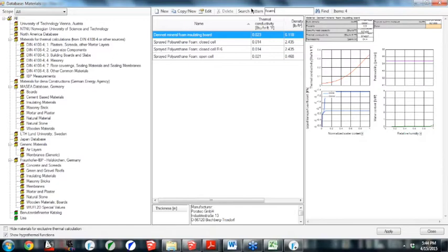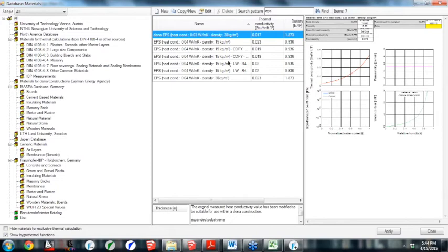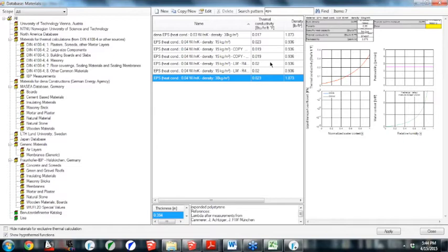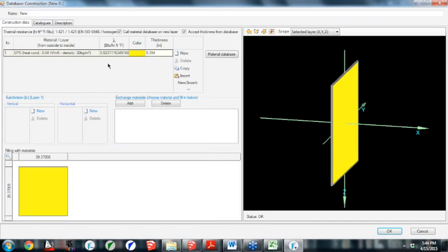It's pretty different in terms of the actual composition of the material, but what we're looking for, again, is just the R value. So yeah, the density of foam glass is going to be significantly higher than this, but we're just going to pick this value for the EPS and use the R value from it. What we could do, if we wanted to run a dynamic model, is actually find the information for foam glass and create a new material within our material database. I'm not going to do that today because we will run out of time, but that is something you can do. Okay, so we have 6 inches of foam glass under the slab, and now we have a 4-inch concrete slab.